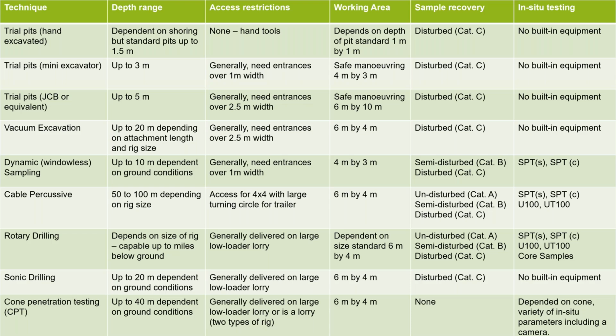What I haven't mentioned on here is the cable percussive rig actually has a different type of rig as well. There is something known as a cut down cable percussive rig. So the cable percussive rig in itself is quite tall, nearly 3 meters tall, but you can get a cut down version that people can manhandle into basements. So that's also worth considering.